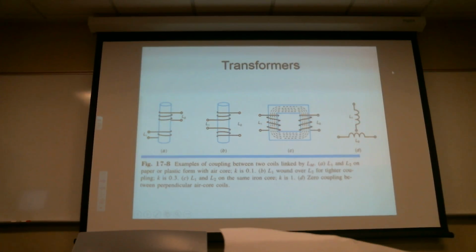Oh, absolutely. Because a permeable core means all the magnetic lines of flux are going to go into there. As they form, they're going to build up and stay right in there. If I don't have a permeable core, they're going to be out in the air, and then come back down. So the effectiveness of this can change if I move a permeable core in and out of there. So I can cause this thing to be quite a bit inefficient if I wanted to.